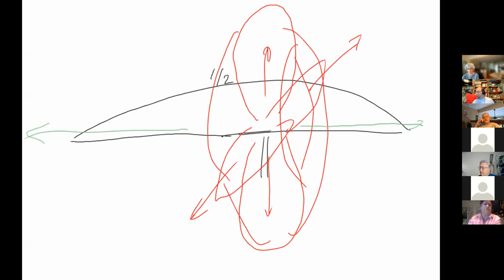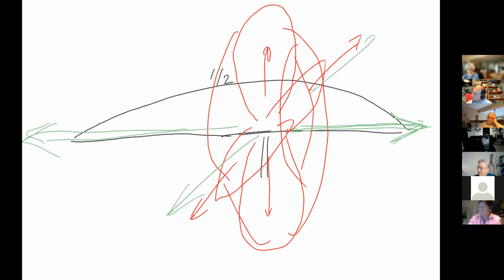Yeah, there's basically nothing, which basically means that a half wave dipole antenna makes a pattern that has virtually no energy emitted along the line of the wire. This is known as a broadside antenna because the energy is transmitted perpendicular to the antenna, or broadside. Is that technically a torus? It is. The shape that it makes is actually a torus. And it peaks at its center. It peaks perpendicular and then it goes down as you go around, and that actually forms a torus.